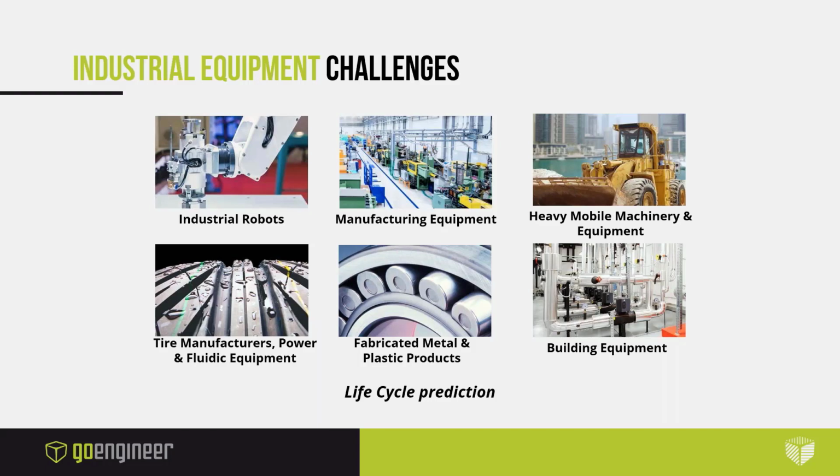So what this involves is they're not only statically testing their components, but they're testing their components in dynamic and vibration environments. And one key area of interest for a lot of these companies is life cycle prediction. Not only do they want their components to survive for a single loading cycle, but they want their components to survive for multiple loading cycles and essentially ensure that they have good fatigue life.